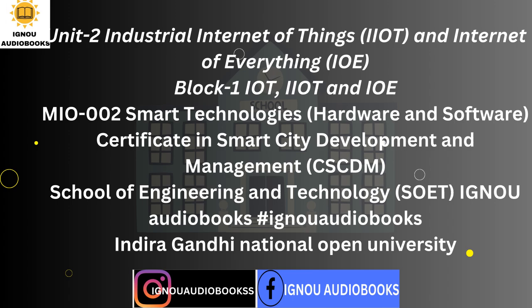Middleware, platform. The middleware is usually the historian software, which most plants already have at both the plant and enterprise level, but could instead be other software, platform, providing the same shared data acquisition, storage, and access security functions. The historian, or other middleware platforms, collects and archives data from the control system and other data sources in the plant over long periods of time in a shared repository, big data. And they enable access to real-time and historical data to analytics and reporting applications.